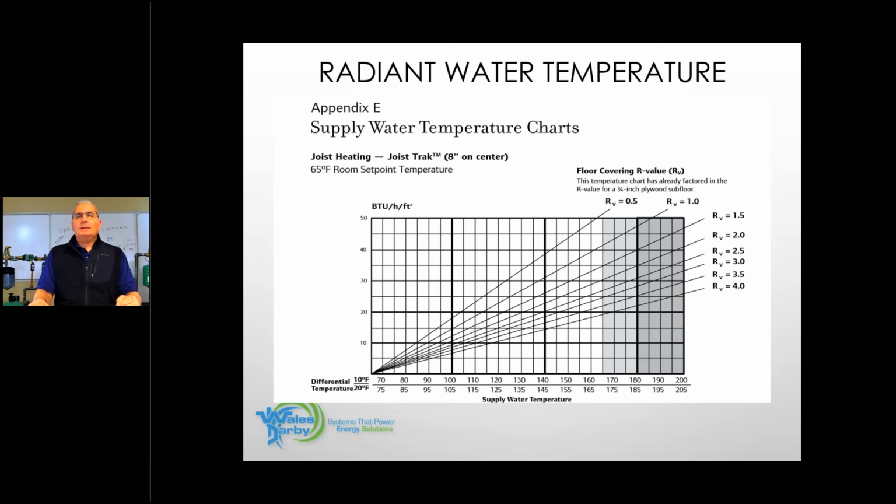But I'm pretty sure it might be closed cell that we want to use, because as it's curing, it creates a tremendous amount of heat. All right. So now they don't have to spray a lot. 1 inch would probably be fine. And then if they want to back it up with paint, that would be fine. So we could be okay, but it's probably going to be closed cell that they're going to use.